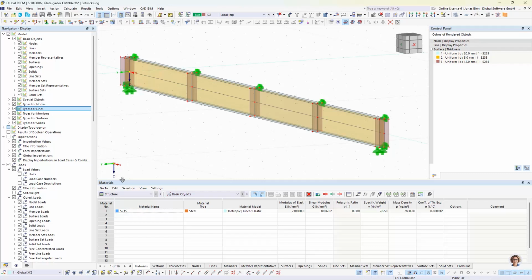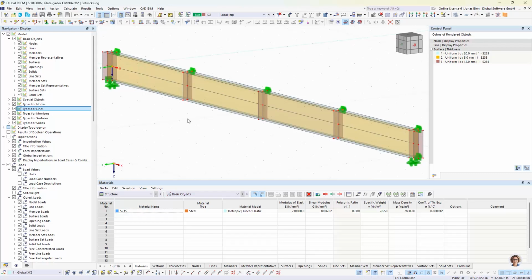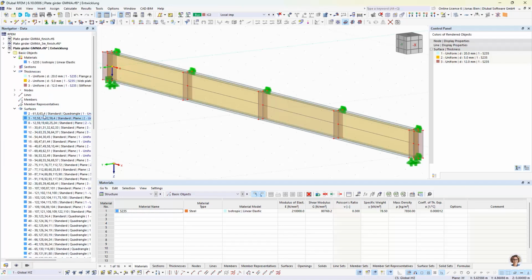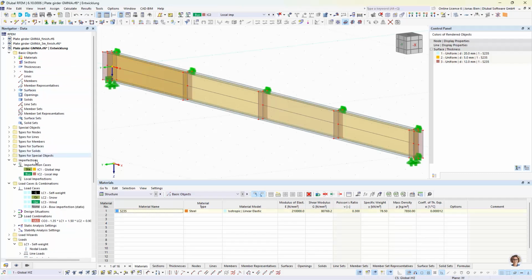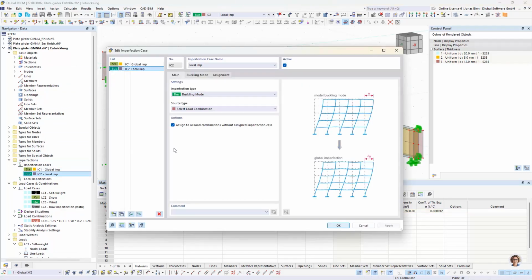So we could either put in a lot of effort to select the most critical one and apply 100% amplitude to this, or we can just, on the safe side, assume the full 100% for all imperfections, and the ones that do not really harm our simulation will just more or less do nothing. Of course, we could refine it later if we find that our solution is not economic, but due to time limitations, I don't want to do that here.